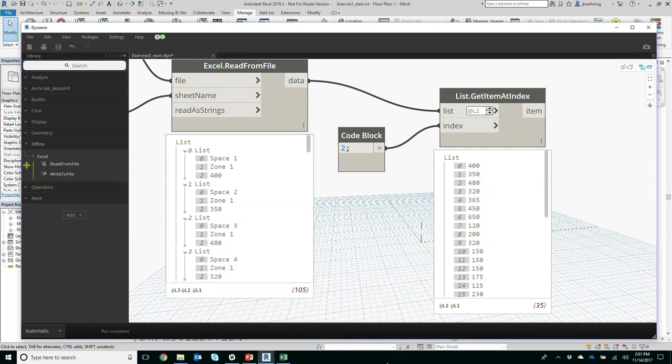Was the levels, did that kind of replace the item indices or something? There used to be a different way to try to... Yeah, so the question was, was there a different way to do it? You could use the List.Map functionality to kind of map it in, and it was really confusing. But now the list at level functionality really helps that.